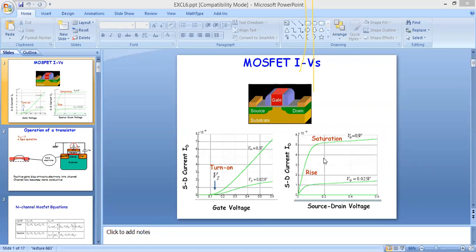If you compare MOSFET with BJT again, you can see the input impedance of MOSFET is higher as compared to the BJT. In terms of size, the size of MOSFET is smaller as compared to the BJT. That's why we are preferring MOSFET. So we can build a number of transistors on an integrated circuit because its size is smaller.